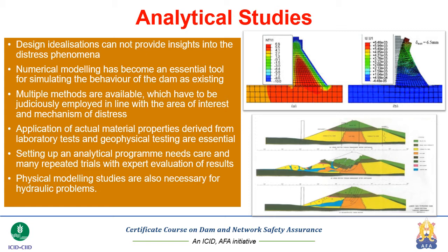Physical modeling studies are also necessary, especially for the hydraulic problems like the erosion. We have a very severe problem of uncontrolled erosion downstream of the energy dissipation arrangements, especially in the ski jump buckets and in the roller buckets, where the mathematical formulations are not adequate. There are various site conditions which cannot be replicated exactly in a mathematical model, but then physical model may also be necessary to see that if we make some changes, how they are likely to perform, or the existing changes that have occurred, how they are actually behaving under extreme floods. So physical modeling as well as analytical modeling are important exercises where some serious deficiencies are noticed, and where the dam has got sufficient amount of importance and resources and hazard potential to undergo these exercises.